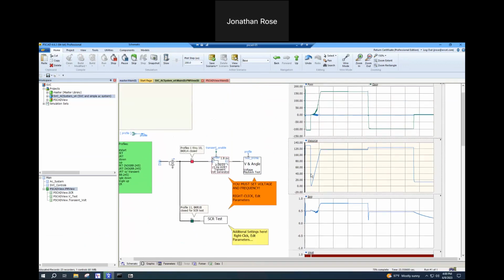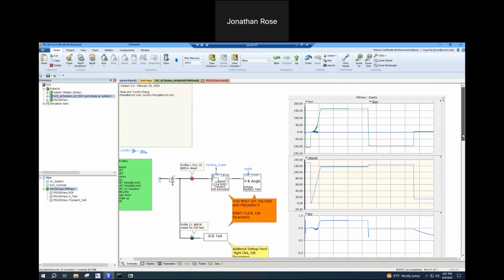There you can see the beautiful LVRT curve that is well known. And there it goes down, it comes back up. And you can see at the very end we have this long period of 0.1 that should trip IBR models to test they have realistic protection.